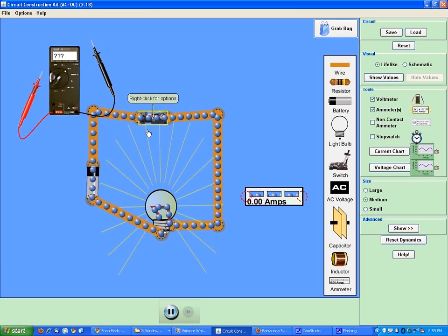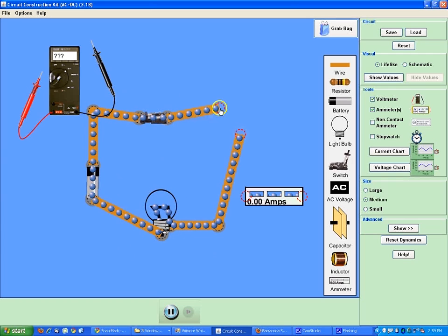When we measure current, we want to break the circuit. That means literally make it so the circuit no longer works. Put a hole somewhere in the circuit. So I would do, in my picture, I would make a hole right there. Now there's a hole in my circuit. It's not running. What do you think I'll replace that hole with? The multimeter. Very good. So you would take your red and black probes, when it's set correctly, and that would replace the circuit and measure all the charge now flowing through there, and leaves again.